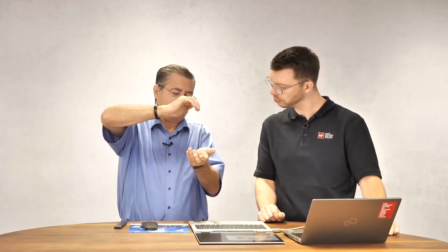Perfect. Are the ferrite beads shielded? Yes, indeed. The ferrite bead, in fact, is nothing else than an air core put into the ferrite package. So it has no gap. It will have saturation with big currents, so pay attention to big currents, but it's completely shielded. There is no escape of radiation. Okay, it's like a toroid. Yeah. Thank you very much.